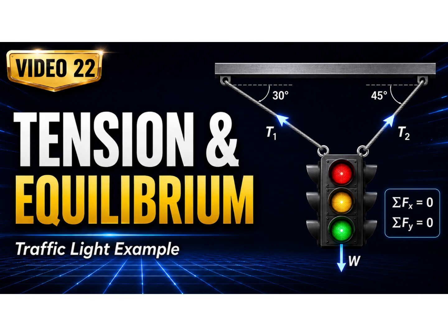By the end of this example, we will use the angle of the cables, the mass of the traffic light, and Newton's laws to calculate the tension in each cable. Before solving the traffic light problem, we need to understand what tension is and how ropes and cables transmit forces.